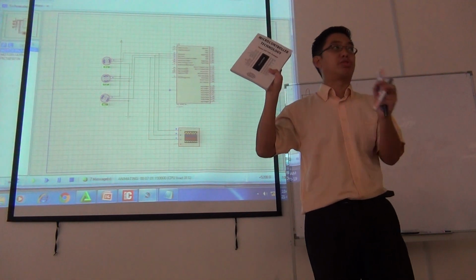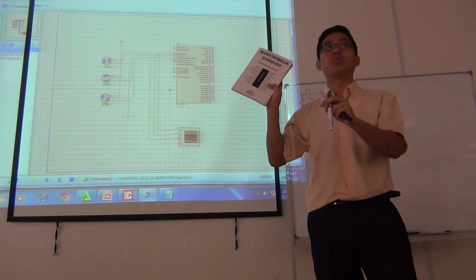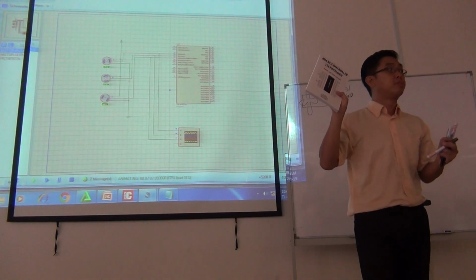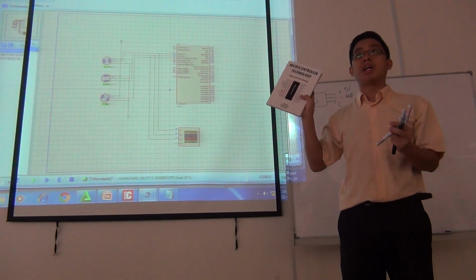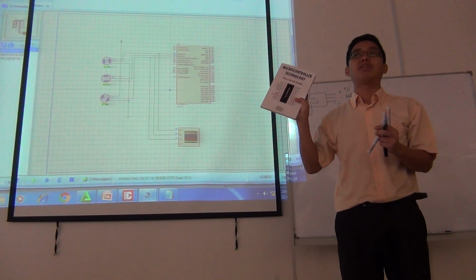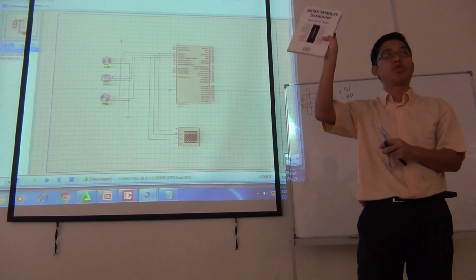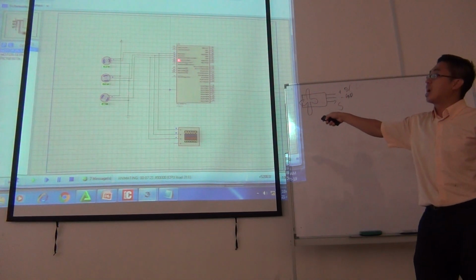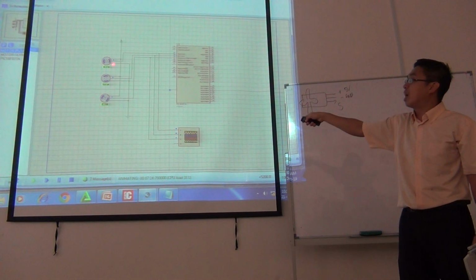So you can choose. When you want to do the setting for port A, you have to choose whether you want to use it as output or as input. For the input, it can be either digital or analog. For the output, it will be only digital. You cannot generate analog output. So look at that. Here is the one that I set up as digital output. Later, I will show you the waveform.